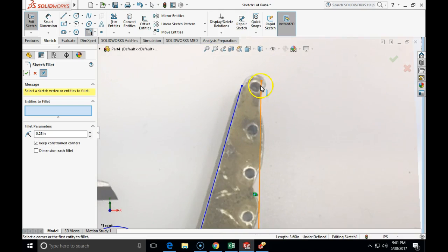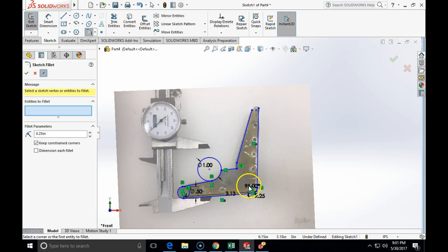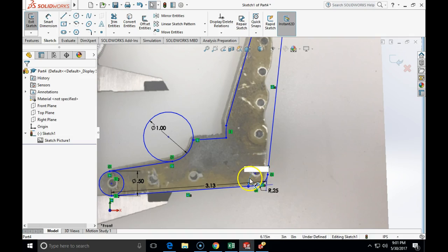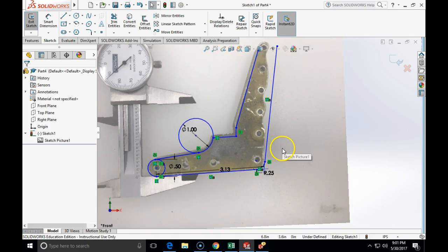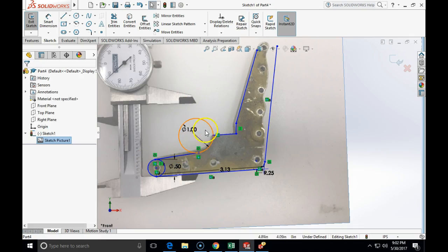What will now bring us to the other end, and we see that this angle of 95 is too small, so let's change that angle to some other, maybe 100 degrees. 100 degrees is too much. Or if we delete that angle constraint completely and redo it again, with the dimensions that we have in place. We just need to be sure that it does not mess up our other relationships. What just happened here?